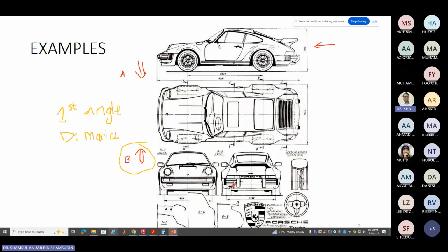This will be the back view. This will be the top view, the side view. Okay, correct. But then again, from an engineering perspective, usually the front view is the view that has the longest dimension. So in this case, this one will probably be selected as the front view, which many would disagree with.